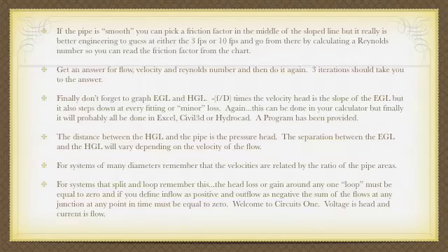And finally, for systems that split and loop, realize that the sum of the head around one loop must be equal to 0, and the sum of the inflow and the outflow at any one point is equal to 0.